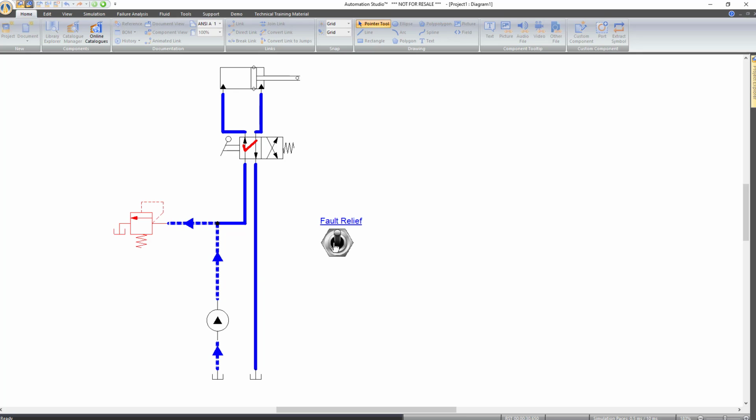So the interesting part of this is that the students can actually trigger the faults. You can first start with all the faults off and confirm the circuit works well and everything. But then when the student turns it on, something is wrong. In this case, it's kind of obvious because if I just retract here and I flip it, it's kind of obvious to know what the problem is because we see the flow going through the relief, okay?